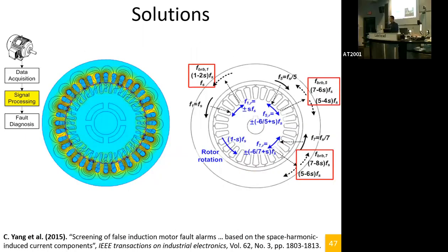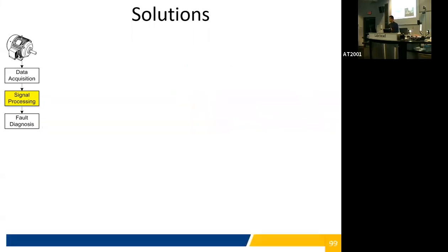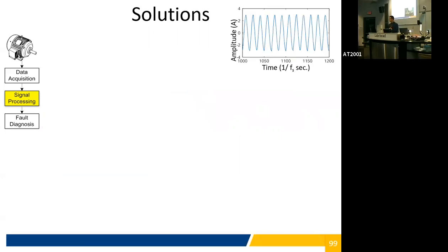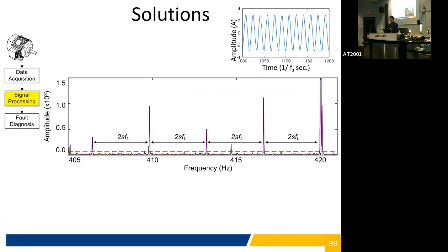And so a solution to that is to look into different higher frequency harmonics. We can see from this publication that these higher frequencies are more concentrated within the stator windings, and are less influenced by a connected load. So the realization of that kind of solution looks like this. So we got the time domain signal again, and a higher harmonic.